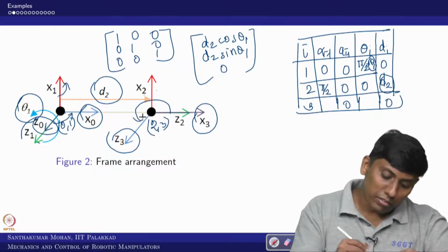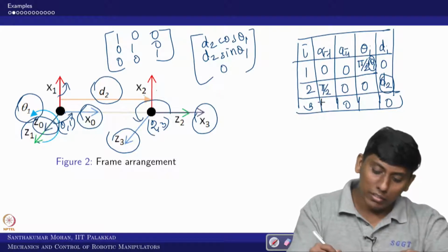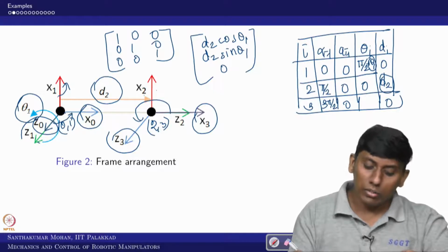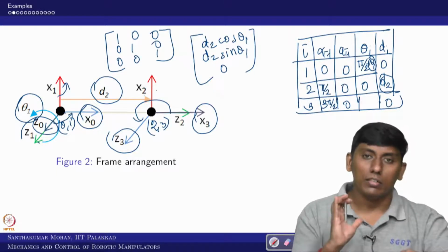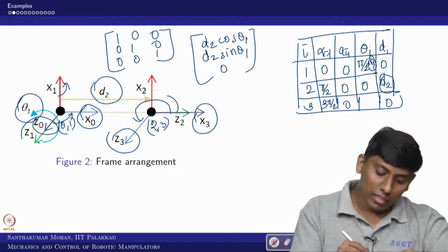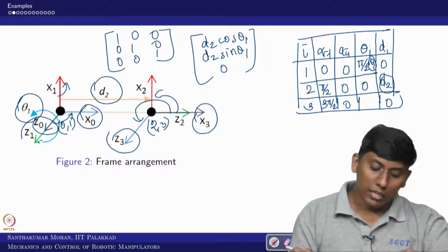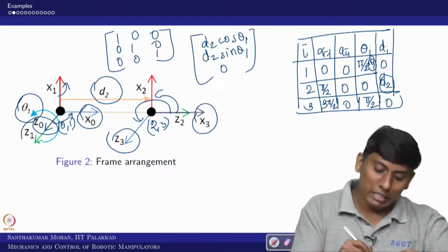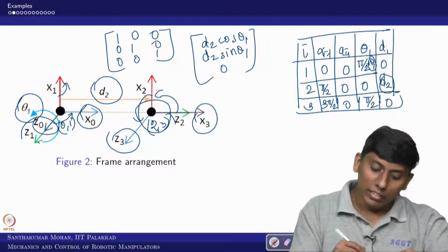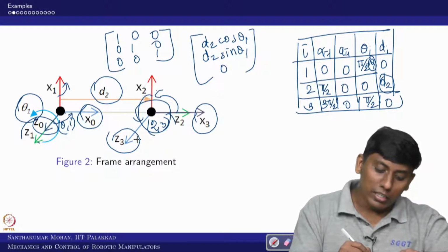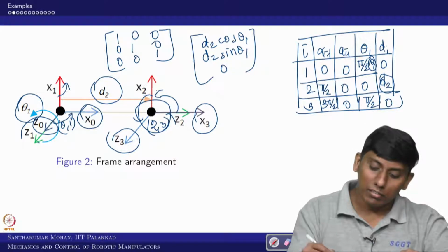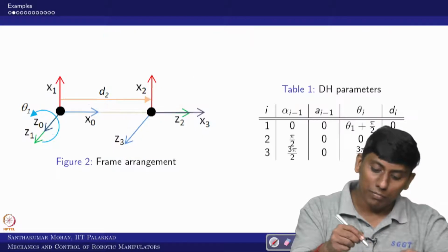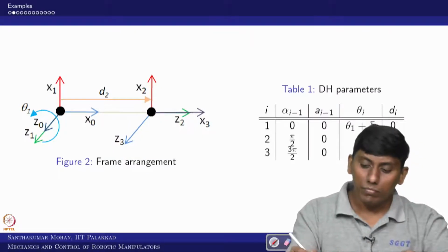rotated 270 degrees to make them coincide, in the sense 3 pi by 2, right, and theta also, there is an angle with respect to z3, you can see that there is an angle, right. So, then you can see that is pi by 2, right, but here this is the rotation, in the sense it is about z3, x2 to x3 distance angle, that is 3 pi by 2, right. So, now this is the DH parameter which we obtain, right.